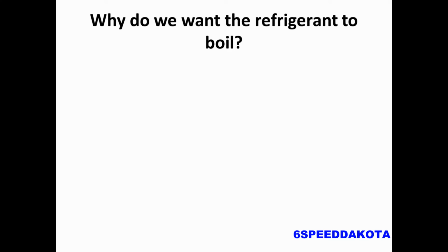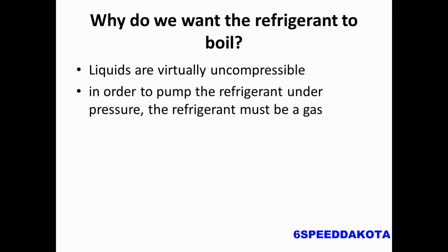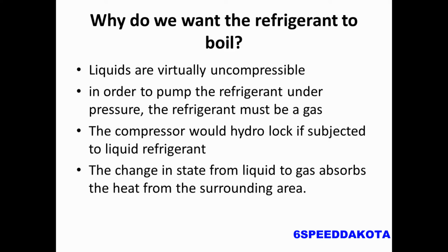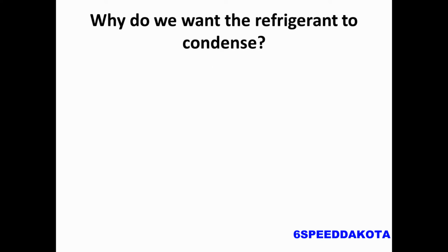So why do we want the refrigerant to boil in the evaporator? Well, liquids are virtually incompressible, so we do not want to send liquid refrigerant into our compressor. In order to pump the refrigerant under pressure, it must be a gas, because if a bunch of liquid refrigerant went into the compressor, it would hydrolock and damage the compressor. So the change of state from liquid to gas actually absorbs the heat from the surrounding area.